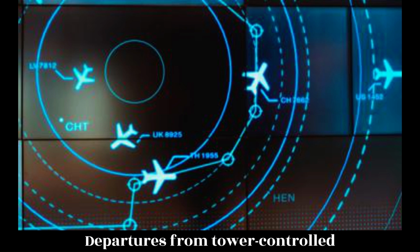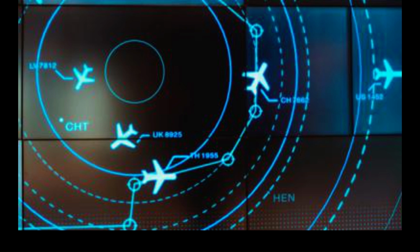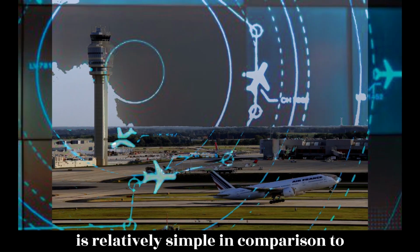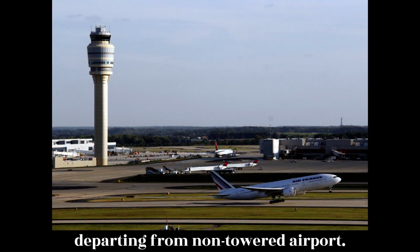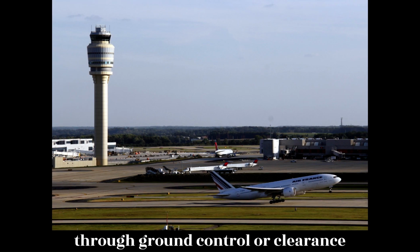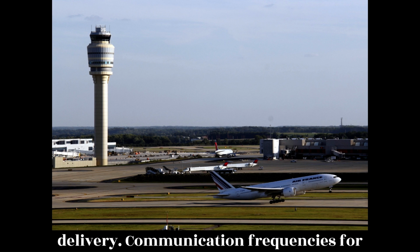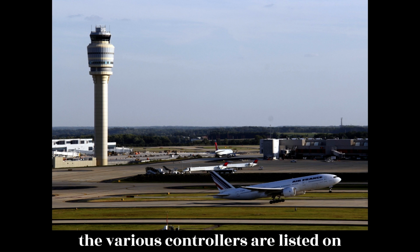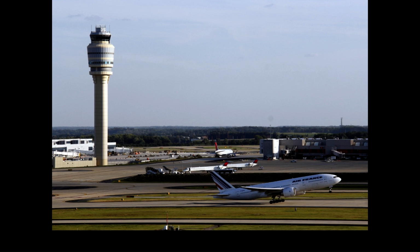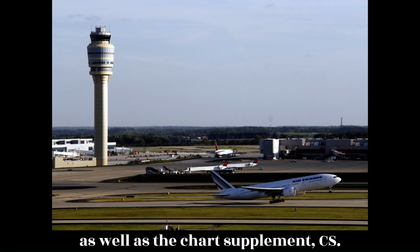Departures from tower-controlled airports. Departing from a tower-controlled airport is relatively simple in comparison to departing from a non-towered airport. Normally you request your IFR clearance through ground control or clearance delivery. Communication frequencies for the various controllers are listed on departure, approach, and airport charts, as well as the Chart Supplement, CS.